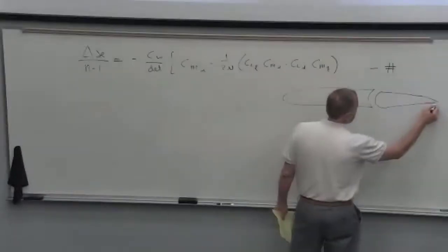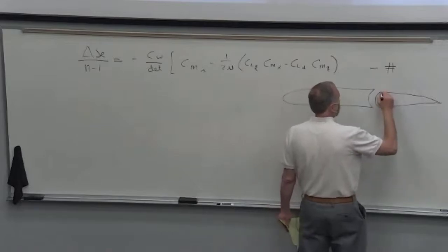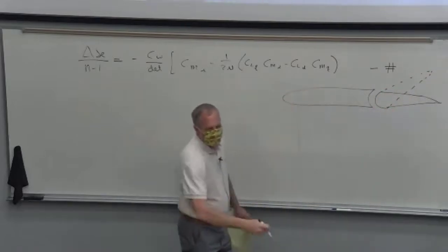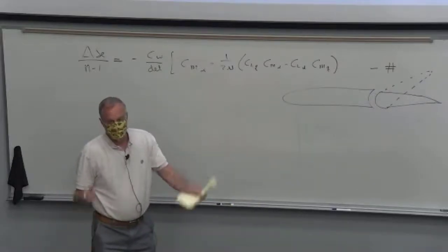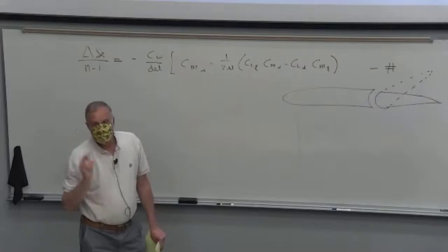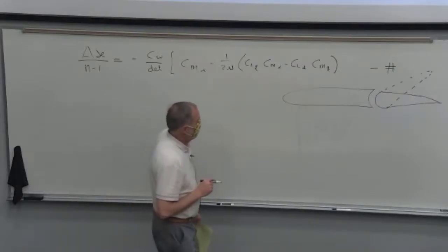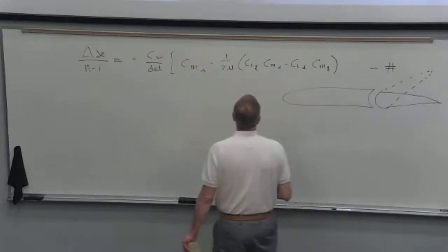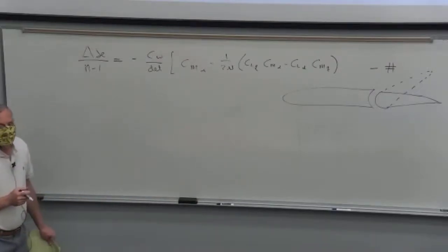there's the elevator on the horizontal tail. We want to pull on the stick, which is negative elevator, to pull the nose up, right? The tail pushes down, nose comes up. We want the pilot to be doing that to do a pull-up. So we want that to be negative, not zero, because if it's zero, then there's no feedback to the pilot.